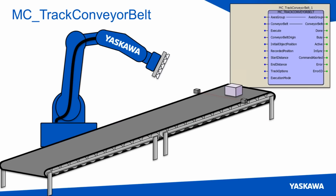So here I have my situation, like I showed earlier. I have a part on a conveyor belt. I have a robot that's going to track that part. And I have a sensor that's going to sense the position of that part. The function block is shown in the upper right-hand corner. It is the MC track conveyor belt function block. The first thing I'm going to need to define in order to use this function block is what axis group I want to be part of this relationship, and what the axis is for the conveyor belt that's going to be part of this relationship.